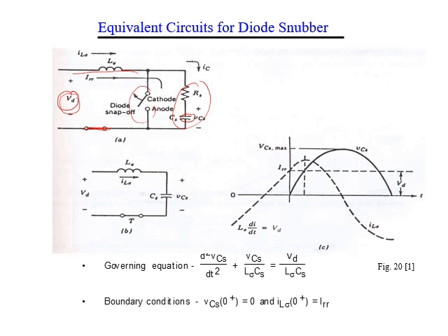So let me start discussing this snubber circuit when we assume the resistance is zero. At the beginning I will assume zero resistance and see the effect of the capacitor only. Then I will repeat the discussion considering the resistance R. If only the capacitor is connected with the diode, when we switch on the thyristor, the current flows through the inductance and then through the capacitor, which represents a short circuit at the beginning.